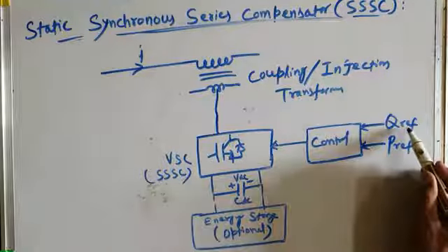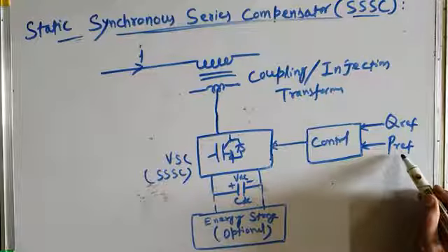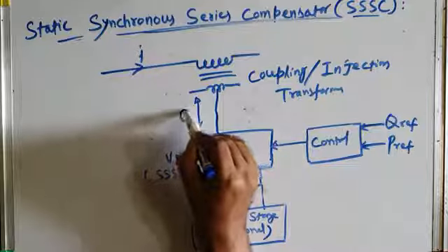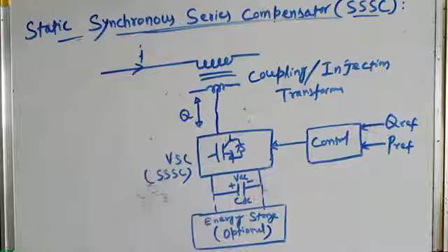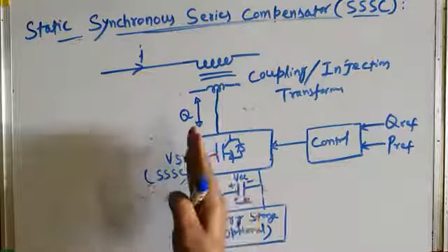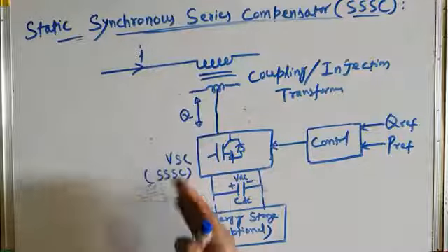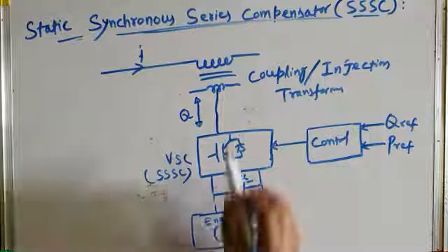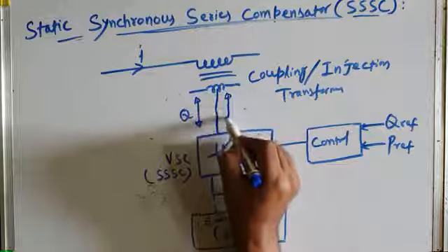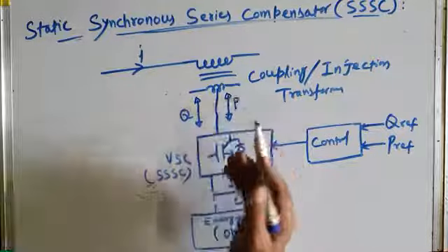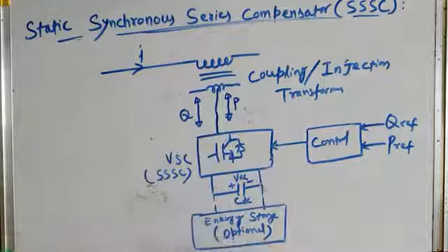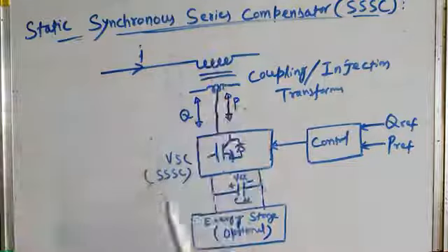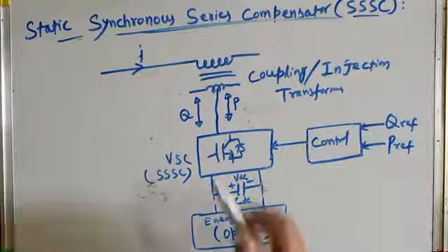QREF is the reference reactive power and PREF is the reference active power. So therefore active and reactive power control in both directions can be done by this SSSC. I mean, it can inject the reactive power or it can absorb the reactive power. Similarly, if it has an energy storage at its DC bus, then it can do the active power exchange also. I mean, it can absorb or draw the active power from the transmission bus, or it can supply active power in series with the transmission bus.